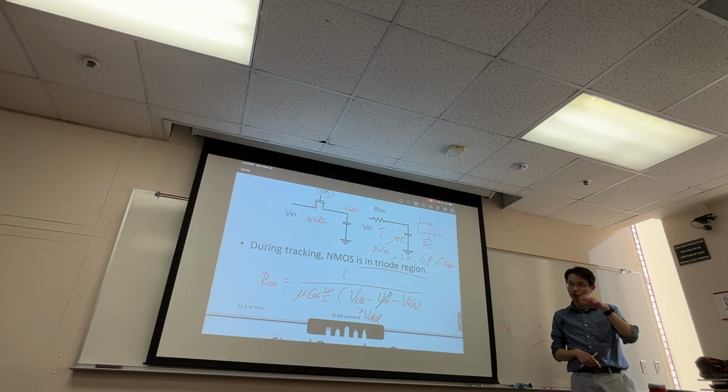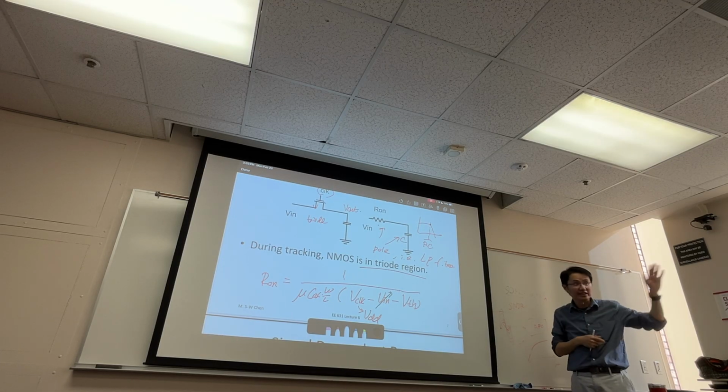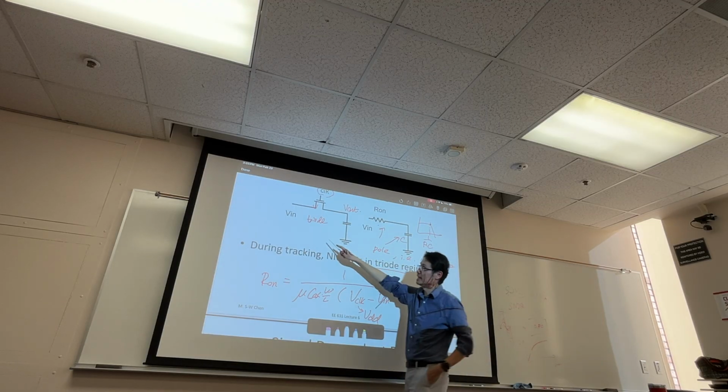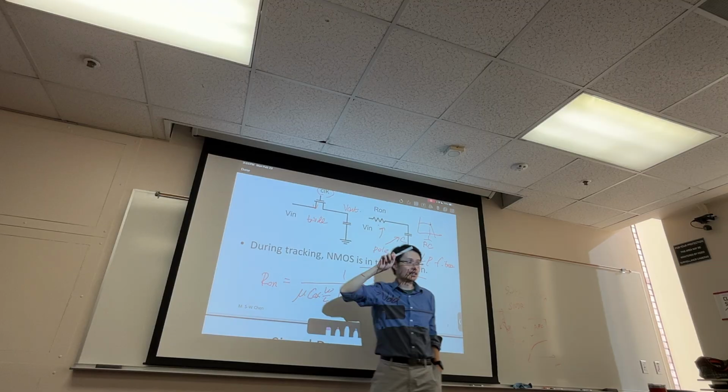So yes, you do need to communicate with them. You say, okay, this is my full swing range, right? The input dynamic range, you have to communicate perfectly with whatever is going to give you that continuous-time analog voltage, to say, okay, this is going to be my upper bound.